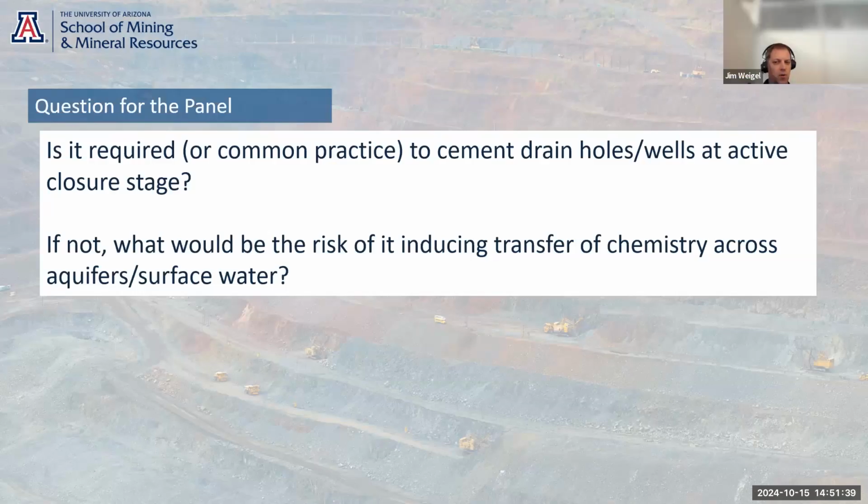The other thing, of course, Jeff's going to say, no open wells. You put a vertical piezometer in every well, drains too, for that matter. There are some places in Nevada where they're actively draining the pit by drilling into something that has no water or much lower pressure heads. So essentially transferring water between different geologic units. So in those cases, it might be prudent to grout up those drain holes if possible.